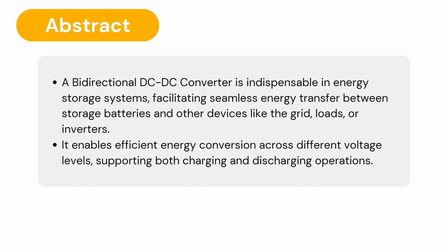In this experiment, I'm using the TL494 pulse width modulation (PWM) processor paired with an IR2111K driver to analyze the bidirectional power flow characteristics. The system's performance is empirically evaluated under transient transitions, steady state loading, and reverse power generative modes, establishing a foundation for higher efficiency energy storage interfaces.